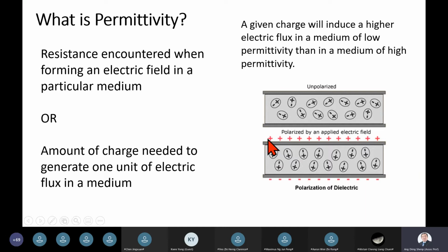For example, if you apply a positive voltage to the top plate and ground the bottom plate, the electric field will point downwards, reorienting the dipoles in this direction consistently, where the negative end of the dipole points towards the positive plate and the positive end points towards the negative plate. In the dipole, there is an electric field that points from the positive end to the negative end. Essentially, when the dipole is oriented like this, there is an electric field that tends to oppose the applied field.